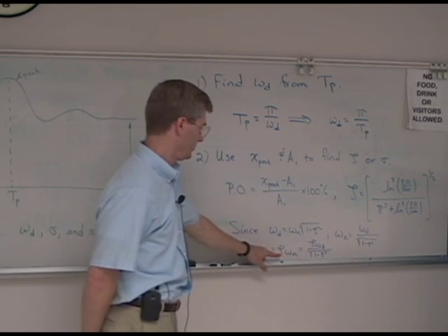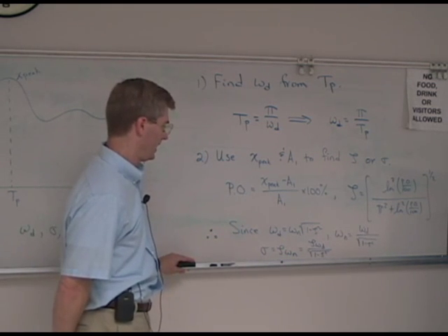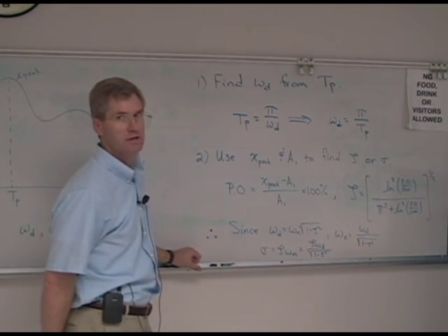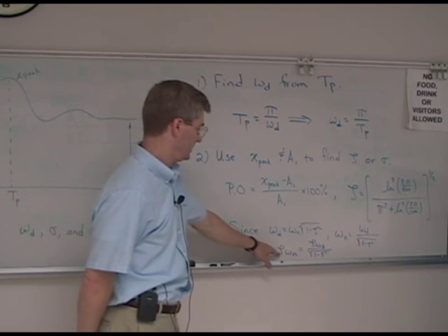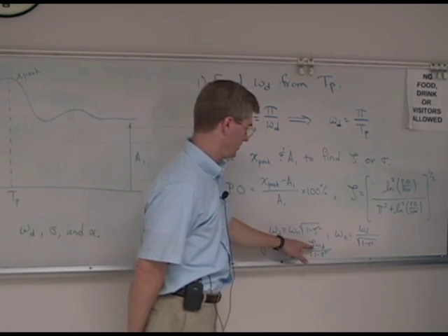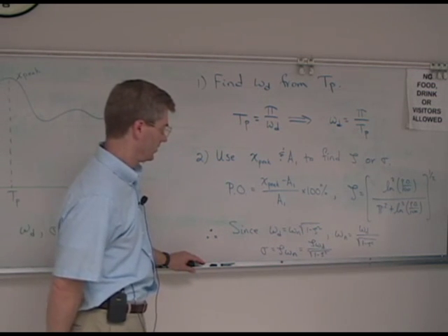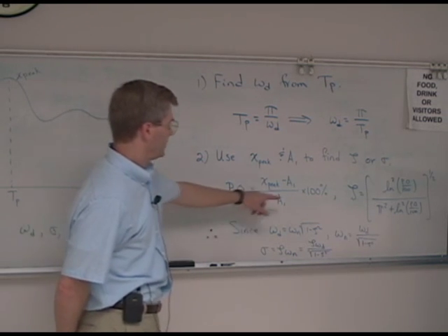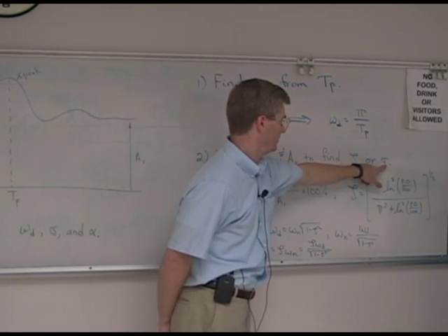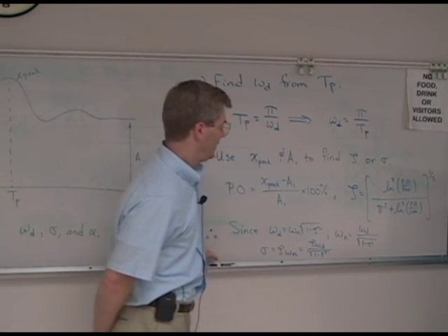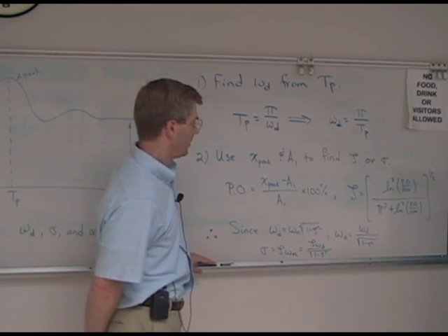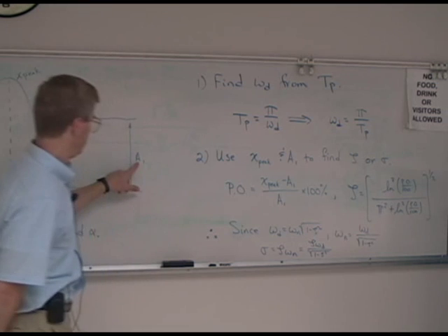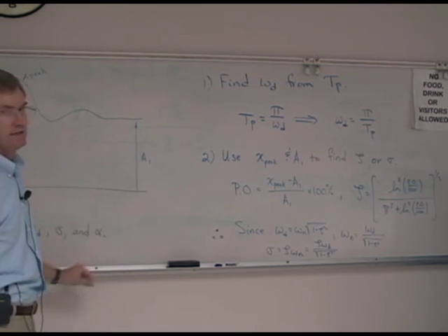Once we have our natural frequency, we can multiply it by our damping ratio zeta to obtain our sigma value, which is the real part of our complex pole pair. Sigma is equal to zeta omega sub n, or the ratio of zeta and the square root of 1 minus zeta squared times our damped frequency, omega sub d. We now have two of our three unknowns. We know sigma, we know omega sub d, and we will now try to find our last unknown, which is alpha, based on our final value of this particular response, a sub 1.